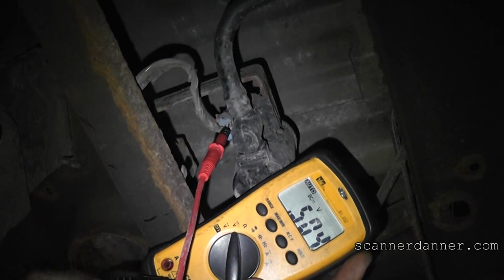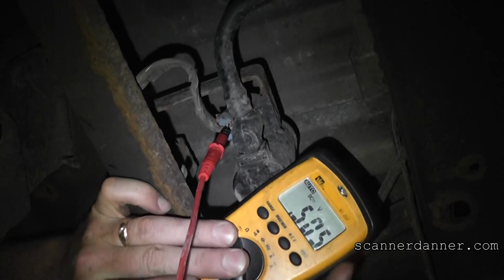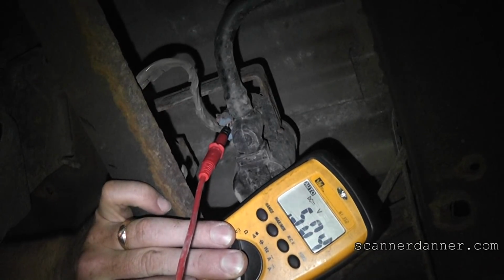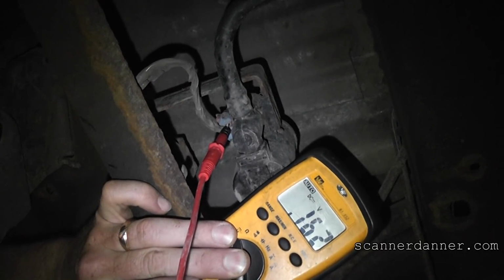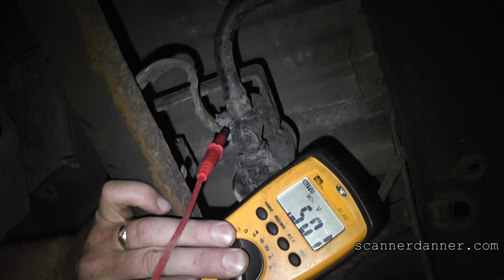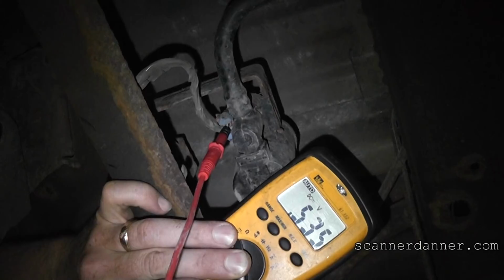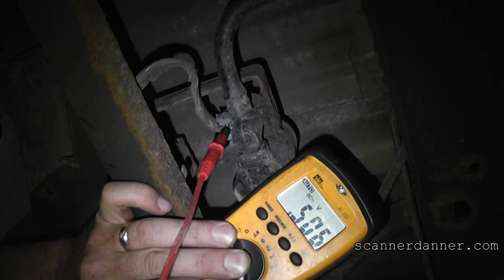It's 500 millivolts. What that's telling me is 2 things. Either the solenoid's being turned on right now, which is most likely not, and I just moved my ground. Did you see that jump around? I bumped my ground by accident. So either my solenoid's being turned on and it has a ground already, or that solenoid is open or has super high resistance.